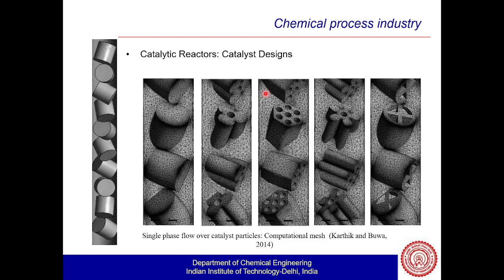But compared to that of the flow problem, the reaction problem will take you maybe two or three times longer. But that is problem specific in nature. If it's a hex grid, it will not take much time. But if it's a grid with a thick mesh, which is unstructured in nature, you will face problems. There are multiple things you have to do in order to get rid of this.